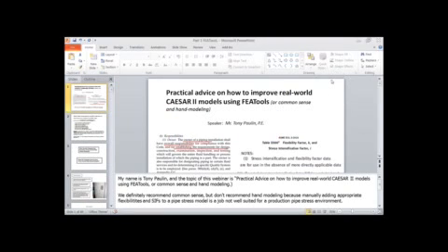There's a couple that were very specific about that vessel model and whether or not it had slotted holes and why it bent the way it did. I guess we could take a look at that after the webinar. Well, the short answer is that it definitely did have slotted holes, and that's a great question. The reason that it bowed was because it was an LNG catch tank. So it had LNG that would collect in the bottom of it, so it would freeze. The bottom would contract and the top would stay ambient, and that would produce the bowing. So the vessel literally bowed. We modeled the bowing in that vessel with Caesar.